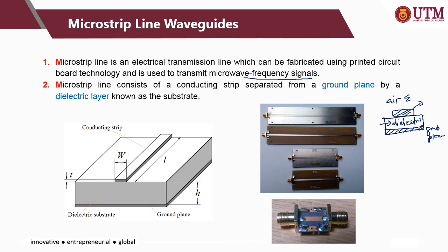So the wave in the microstrip line propagates through different properties. For example, here the E field goes out from the structure through the material, the air or the substrate. So the signal travels across two or more different media, so it is called an inhomogeneous medium.